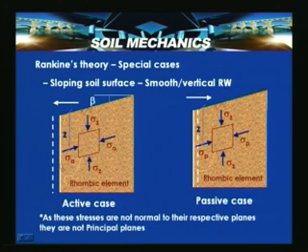So in this particular surface, the wall is initially at this particular position, and when the wall moves away from the backfill, when the wall movement is this side, then it is an active case. So here the fill inclination with the horizontal is beta, that is actually shown here, and which is having a soil which is shown in this element. So in this case, one thing to be remembered and noted here is that the surface is not horizontal.